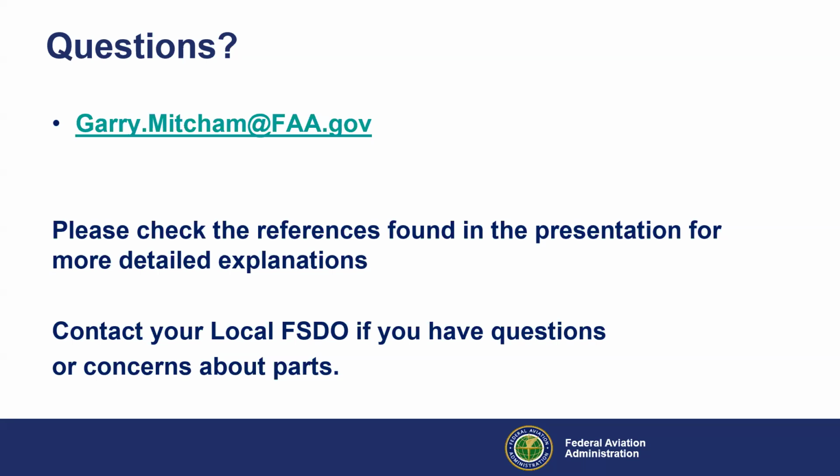I would want that particular part to be approved for return to service by somebody listed in 43.7, because when you remove it from a serviceable aircraft, you don't really know the status of the part. There should be somebody signing a yellow tag 8130 or something that shows the part is approved for return to service. You have to have some indication of that.